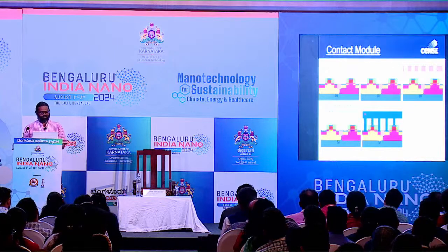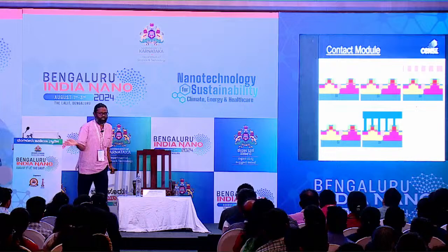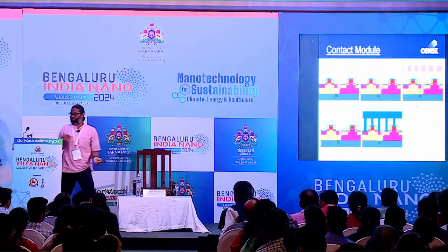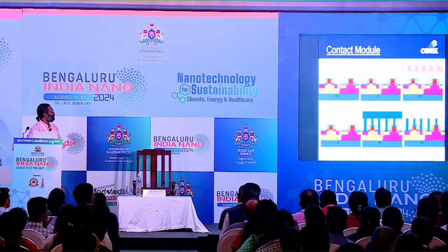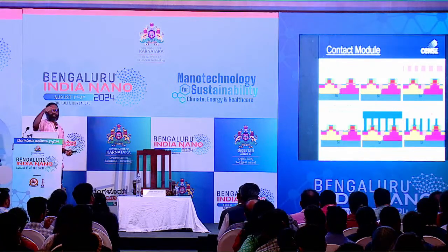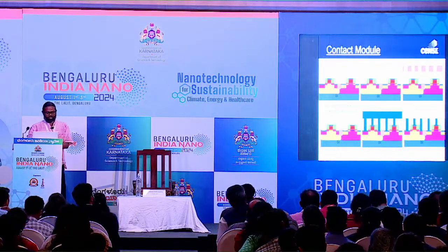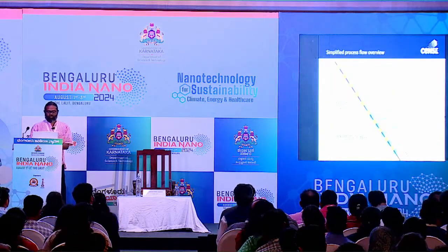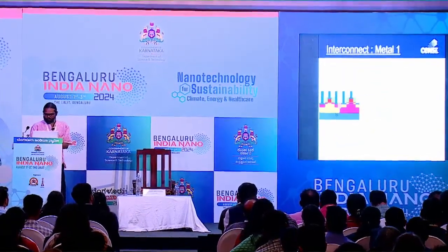After filling this gap, I still have this metal here, which I don't want. They're all shorted now. I have to remove that material. What I do is I polish it and then I can remove this. So now these are all isolated plugs that I have. And now these plugs can be interconnected by using interconnect modules. I'll tell you how that is again.